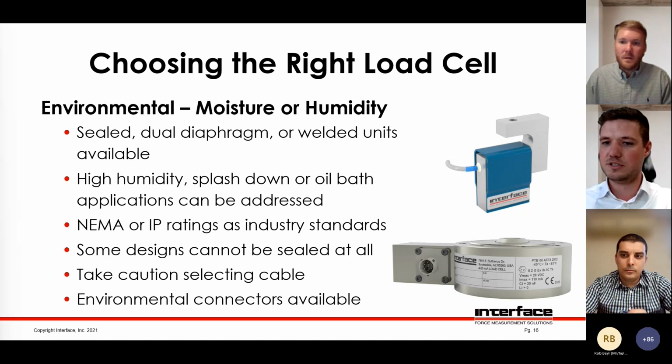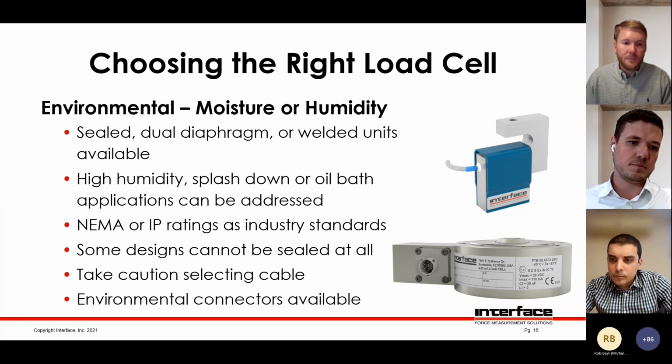So if it's a very high temperature environment, you would need a high temperature cable, or if it's exposed to corrosive material, again, you need a material sheath that is resistant to whichever corrosive material is in the application. We also do environmental connectors that are sealed by IP68, mil spec, or whatever is required there as well.